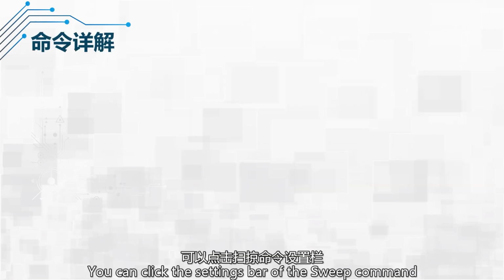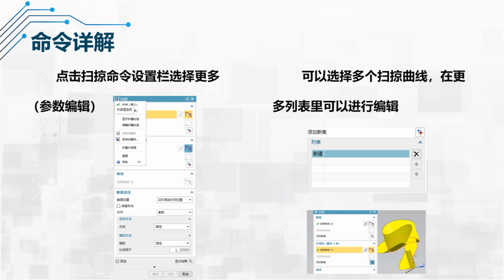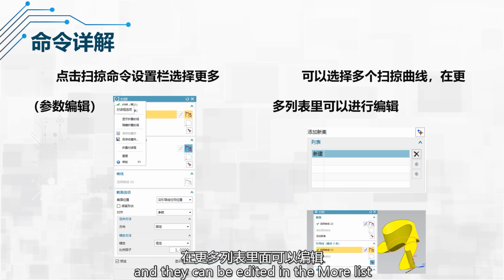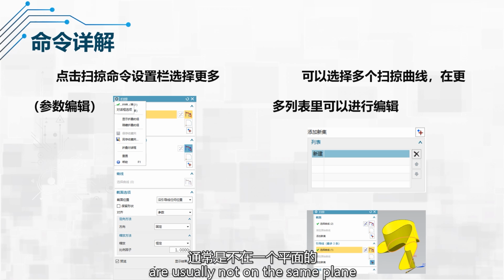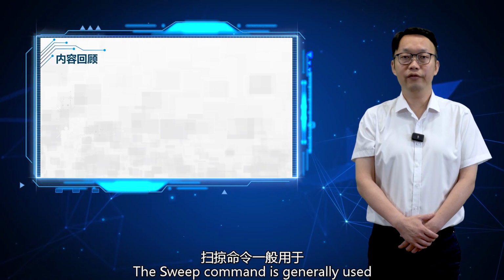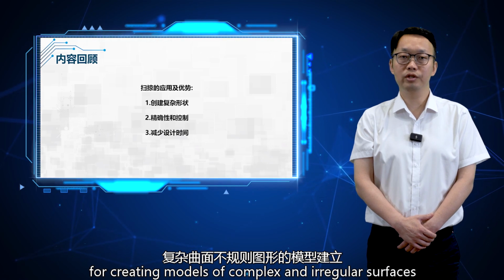You can click the setting bar of the Sweep command, select More Edit, and modify the parameters of the previous options. You can select multiple sweep curves, and they can be edited in the More list. Note that the section selection curve and the guide curve for sweeping are usually not on the same plane. If they are on the same plane, sweeping cannot be completed. The Sweep command is generally used for creating models of complex and irregular surfaces.